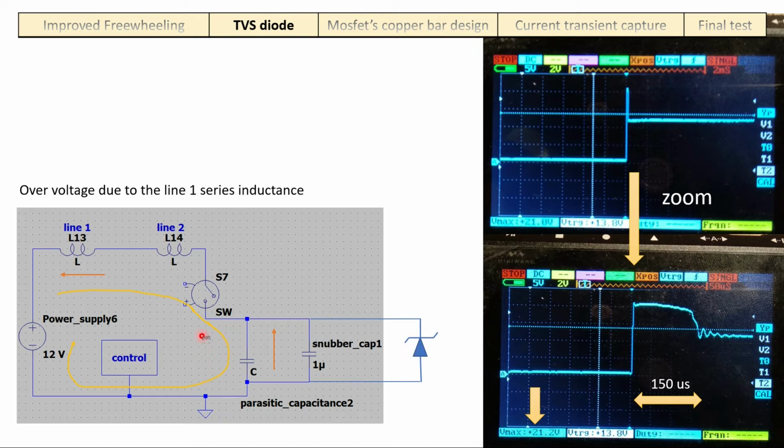This voltage increased a lot. It reached the breakdown voltage of the MOSFETs, and the MOSFETs were close to damaging. They withstood this extra voltage because they were oversized, but they never turned off, because when they were in breakdown, even if the control circuit forced them to be off, they were still in the on position.